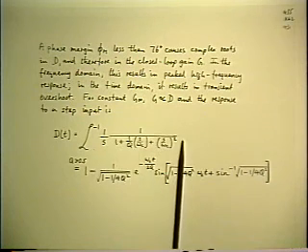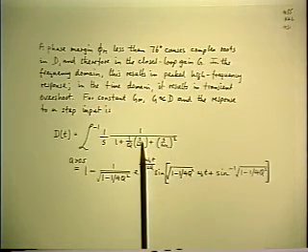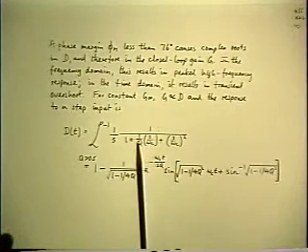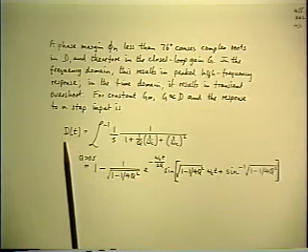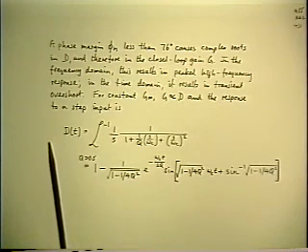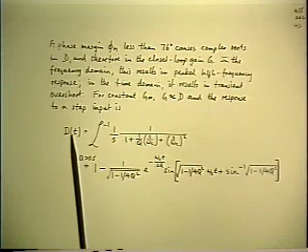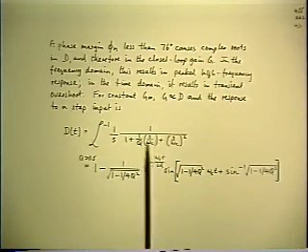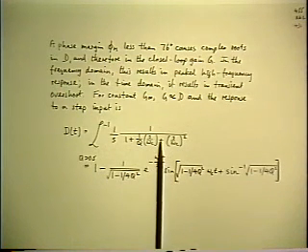And the transform of the gain of the system is simply the gain we already have as a function of S, which, as we've seen, is a quadratic in the denominator coming from the discrepancy factor. The G infinity I've kept out front. In fact, it doesn't matter in this case because we're assuming that the G infinity is a constant. So there's no transient response associated with it. So the time response of the output voltage of your amplifier is proportional to the time response of the discrepancy factor, and it's this function in the case of the two-pole loop gain.